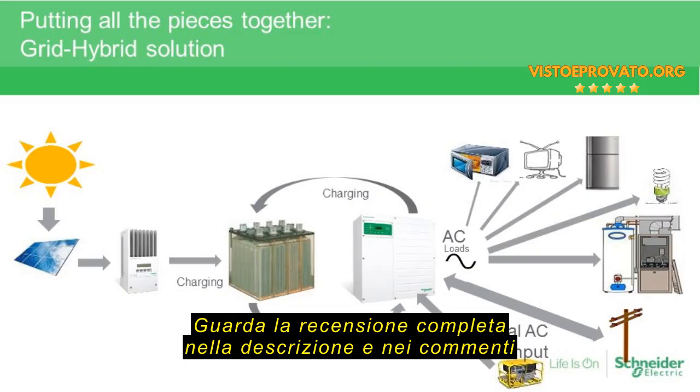One thing that I like to include is the idea that if the house is heated or the water's heated with gas, typically gas services are not interrupted during a power outage. So one thing that is definitely worth looking into to add on to the system would be the furnace as well as the hot water tank heater if they're run by gas, because the power consumption for those is fairly minimal when we're not using electricity to generate heat. Not a good idea in general to try to heat hot water or heat a house with electricity during a power outage. You're suddenly looking at a very, very large battery bank.